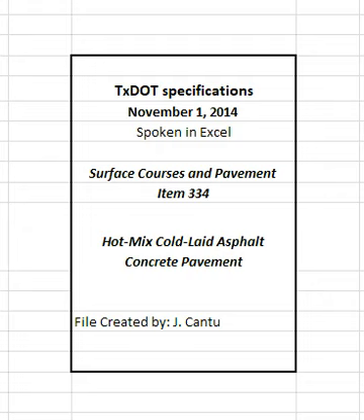Offset longitudinal joints of successive courses of mixture by at least 6 inches. Place mixture so that longitudinal joints on the surface course coincide with lane lines, or as directed. Ensure that all finished surfaces will drain properly. When desired, dump the asphalt mixture in a windrow and then place in the finishing machine with windrow pickup equipment unless otherwise shown on the plans. Prevent the windrow pickup equipment from contaminating the mixture.